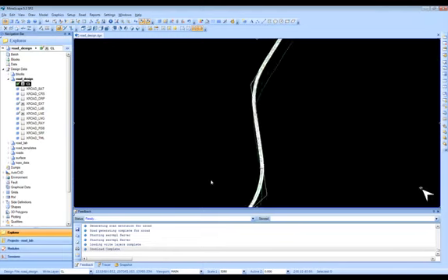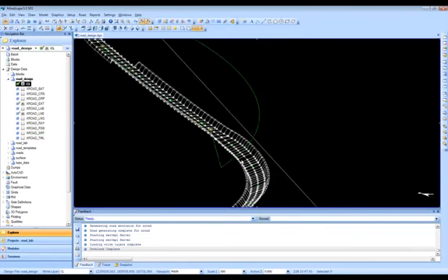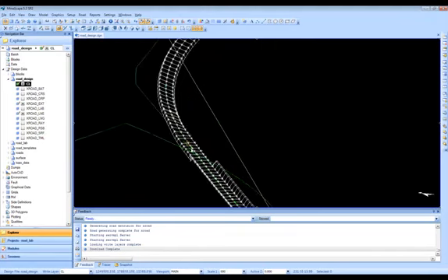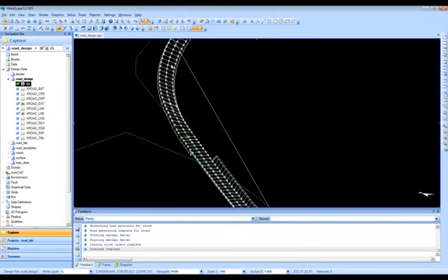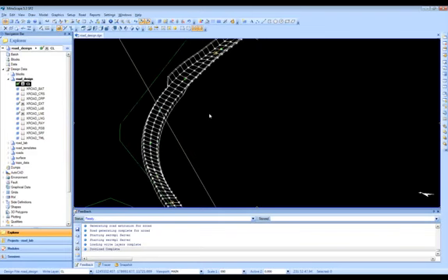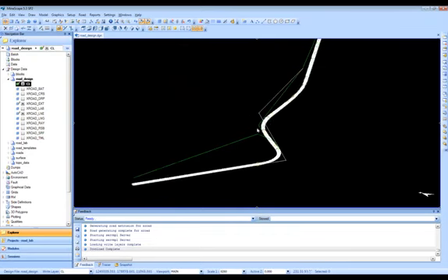And again, if I turn that up on edge, you can see the berms here. So this is a fill situation here, and then it comes into a cut situation, which is where my ditch is coming in to the design, and then back out to another fill situation. So that is basically the cross-section of my road extruded along the center line.